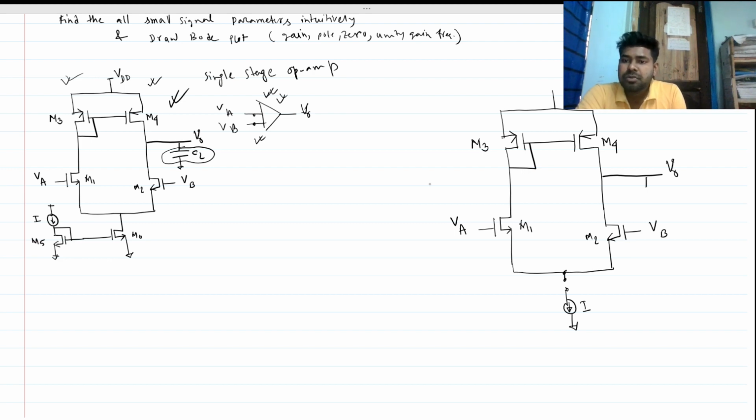Don't be afraid of these two tail MOSFETs. Basically this makes a normal current source. If these two are identical, then the same current I flows through this branch, in DC condition. We already assumed that the whole circuit is operating well in DC, so all the MOSFETs are biased in saturation.